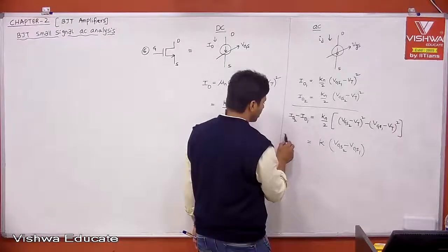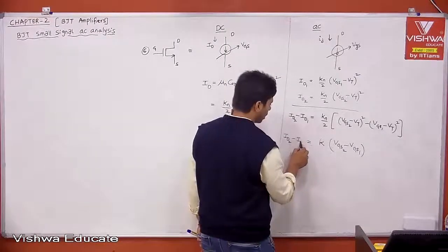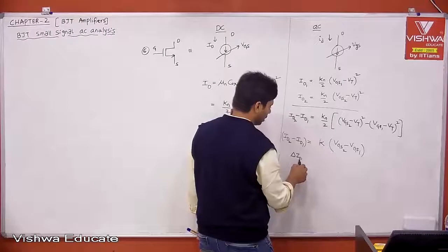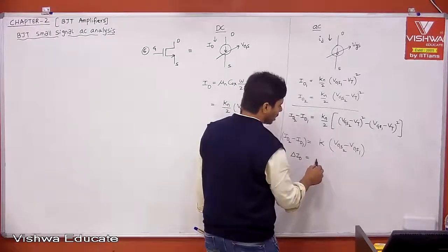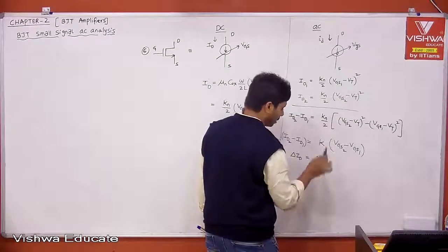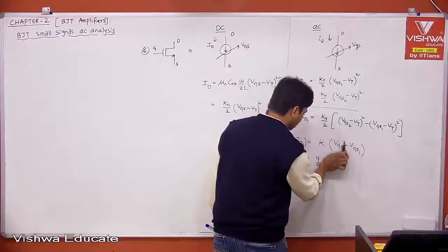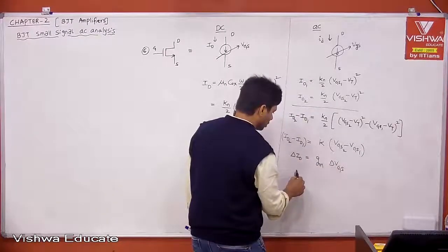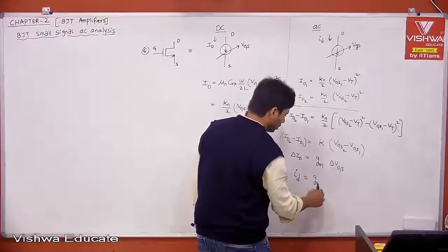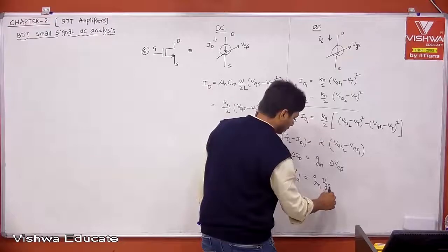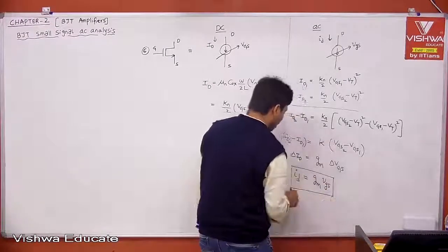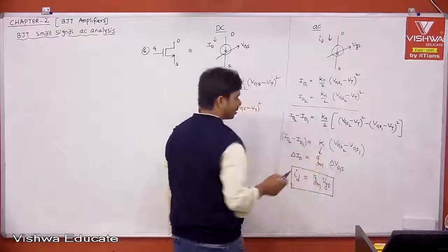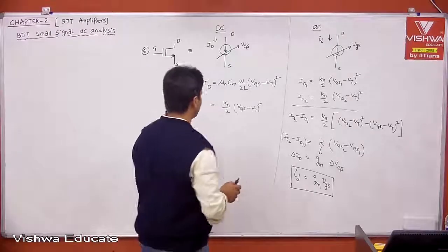Therefore, what is ID2 minus ID1? That is nothing but delta ID, equal to some constant into delta VGS. That constant is nothing but Gm. Why it is Gm, I'll explain later. Therefore, small id is represented as small id is equal to Gm into small VGS. But what is that Gm and all, I will explain later on. For the time being, you can take it as some constant. Now, if you see here, this is your id.